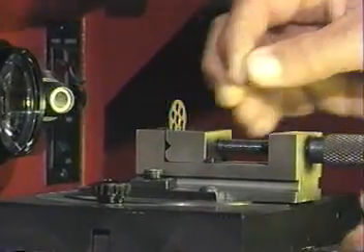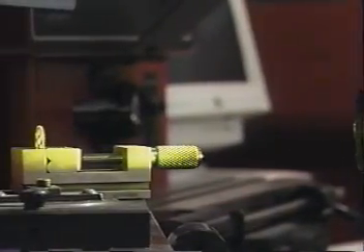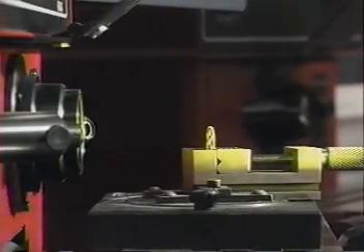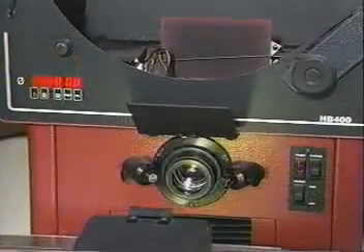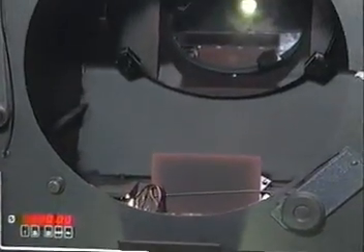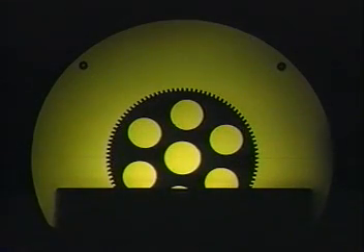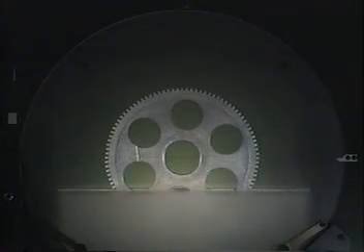The typical optical measuring projector has a stage where a part is mounted. Additionally, optical measuring projectors have an optical path made up of a light source, condensing lens, magnifying lens, and reflecting mirror to bounce a precisely magnified silhouette profile of the part onto a viewing screen. A second illumination source is used to view the part's surface.